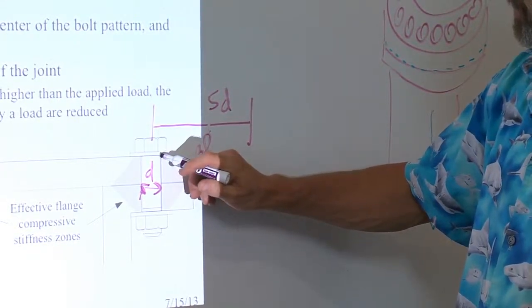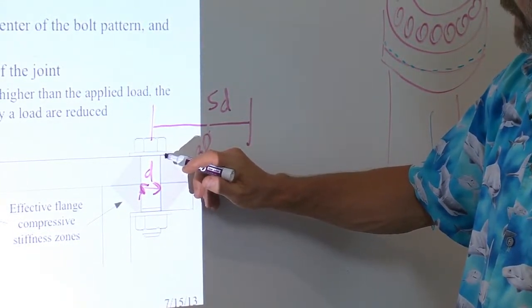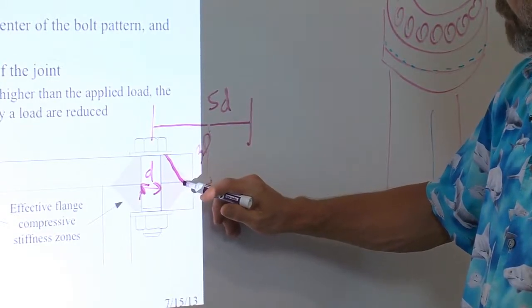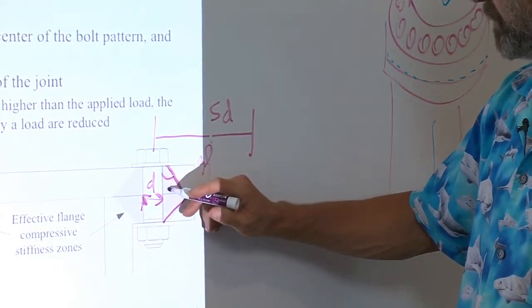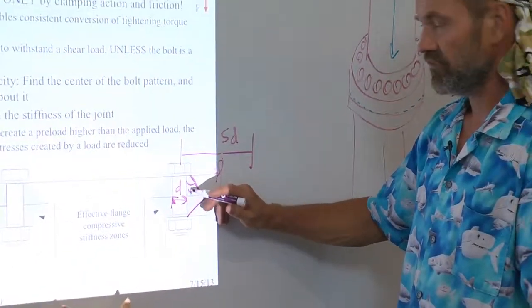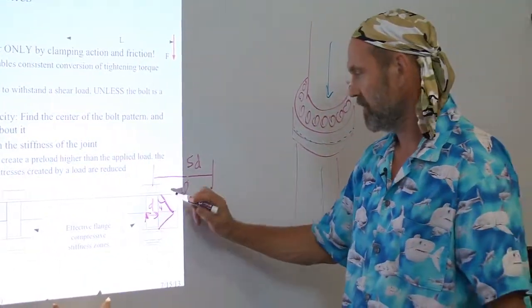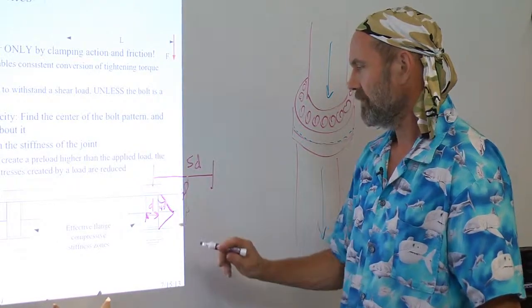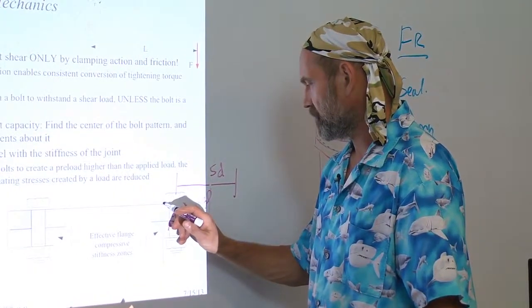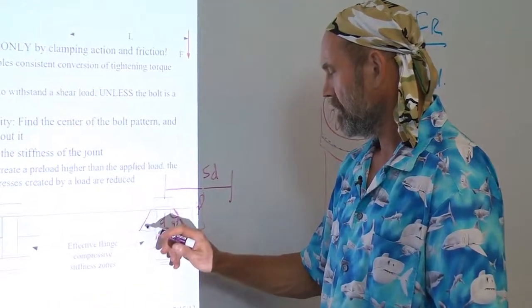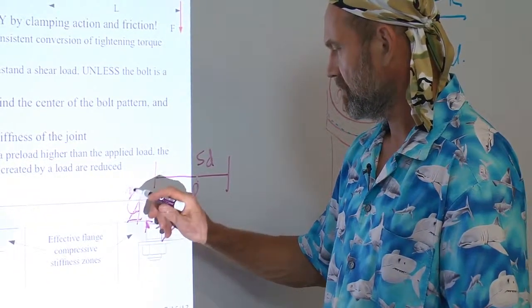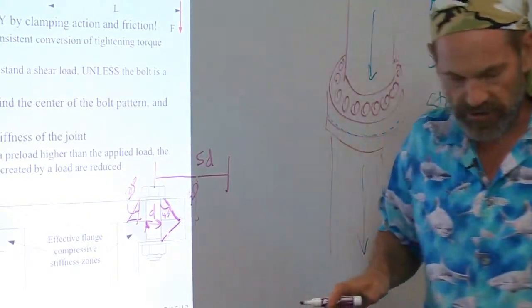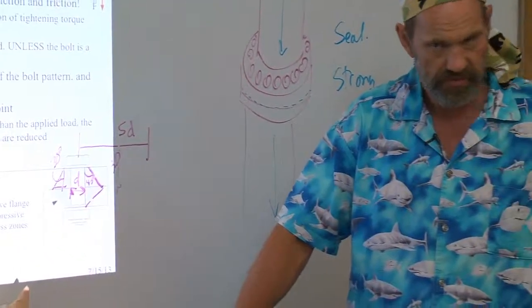And what happens is that right under the bolt head, you start sending out influence. And this angle here, in the worst case, when you're trying not to have it bother you, is 45 degrees. If you're trying to design a joint to not leak, then I do the more conservative 30 degrees. These are the stress cones that emanate out from the bolt.